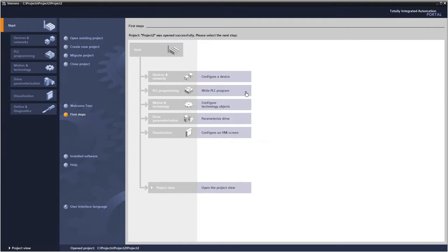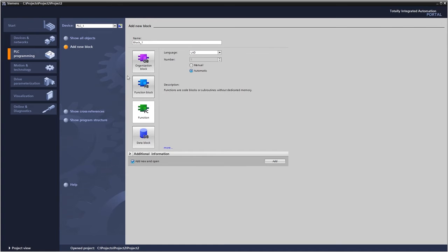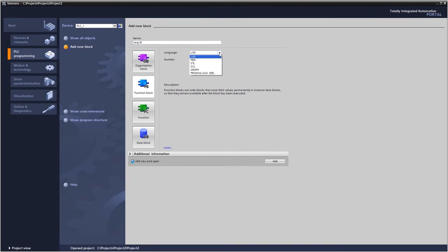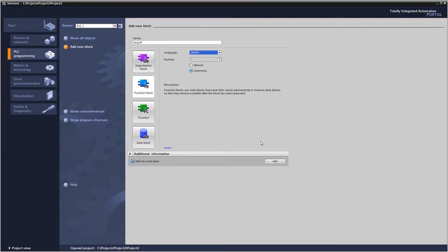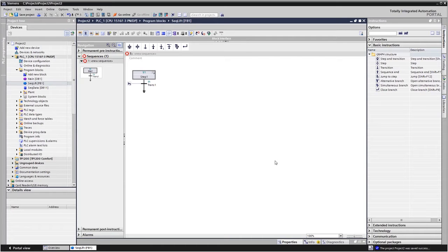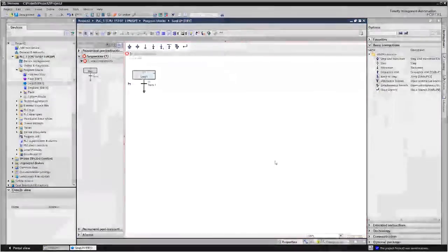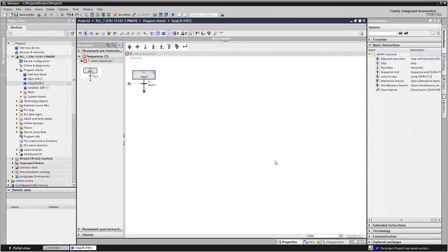How does that look in the TIA portal? In our example, 2 lifting units are to be controlled. To do so, first create a Graph function block in your project. You program the sequencers with a Graph editor. The program window offers a function bar, navigation and an operating range. Via the function bar, you can switch between the views of the operating range, for example.